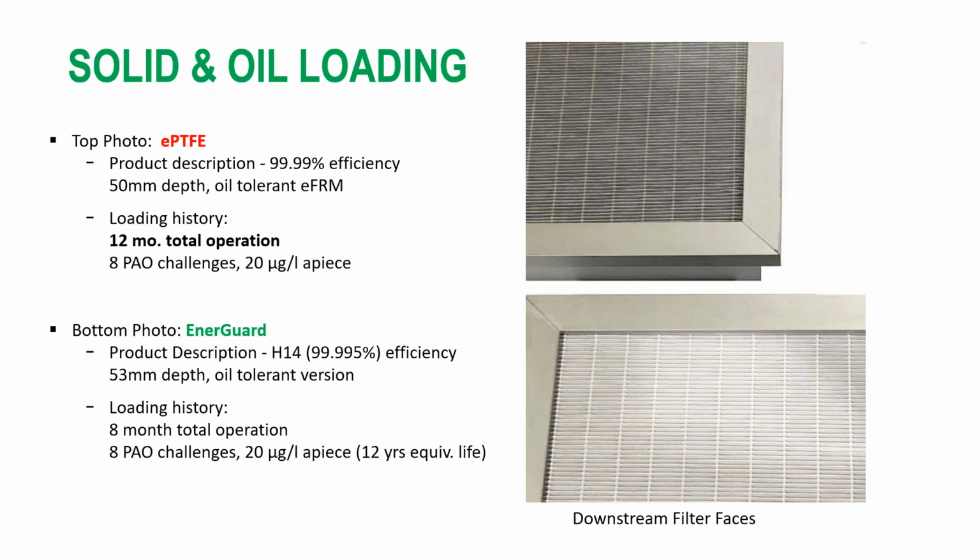One of the issues that we've seen is very quick loading. The ePTFE is available as a media that's both resistant to oil and not resistant. So for microelectronics applications where there's no PAO, polyalphaolefin, challenge testing, which there typically is in biocontainment and life sciences, you would think these filters would last extremely well.